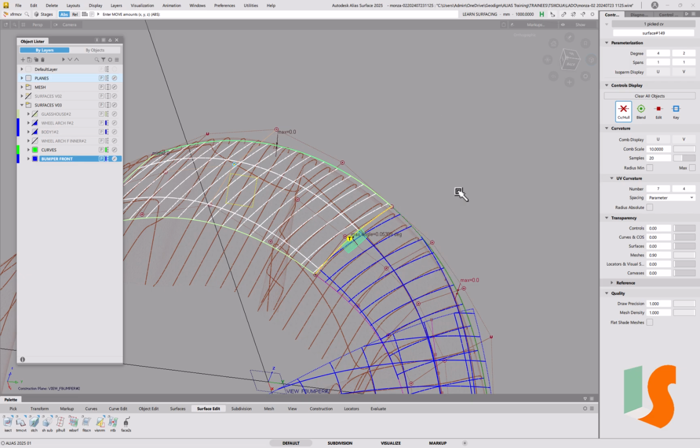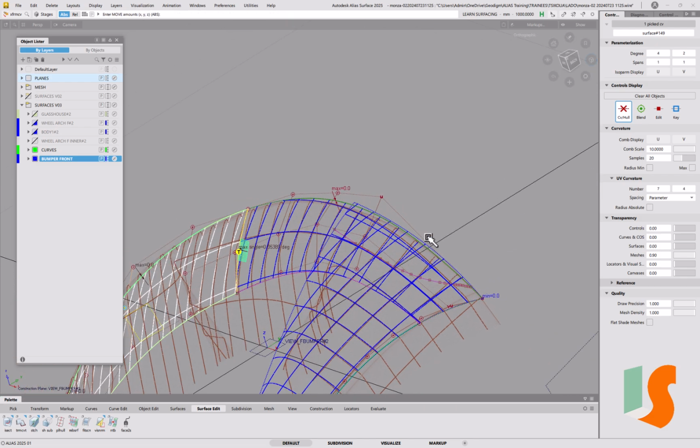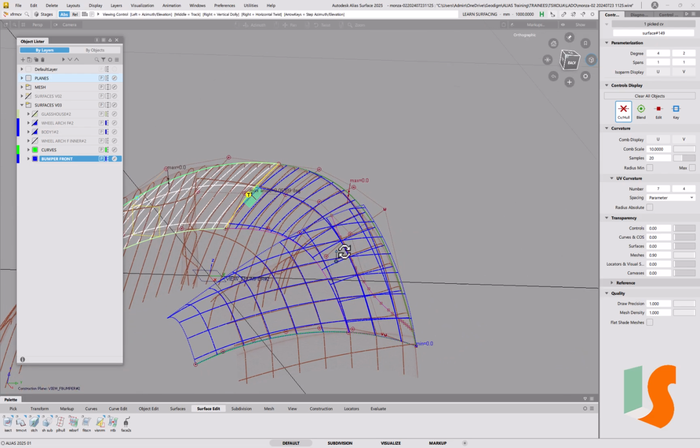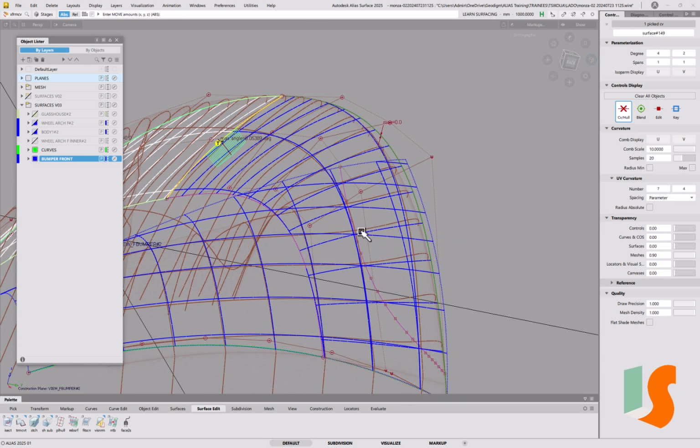Let's put a bit of mouse sensitivity on there, slow it down a bit. So I can see when I do that, then it brings that intersect down a bit. Because there's only a shallow angle between there, this is really going to wash out to nothing, and so it's not like this is a crisp intersect where you're going to have a very tight fillet, which would be very noticeable if it was doing something weird. It's going to wash out, but at the same time I don't think that's the right shape of it at all. It sort of looks about the right position there, maybe.